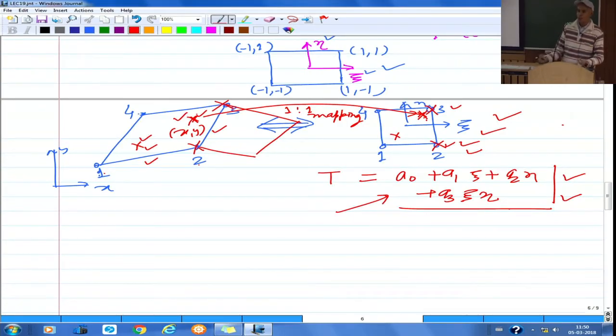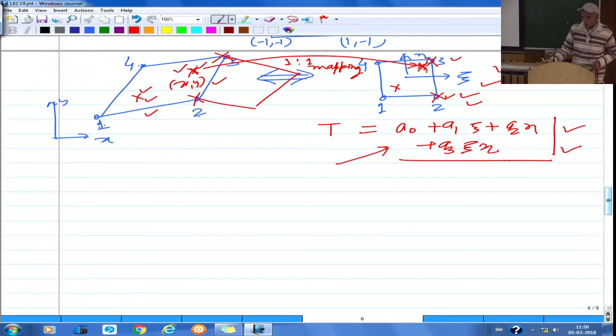And if you do the other way around, a lower order interpolation for x, y and higher order for the field variables or dependent variables, then it is known as subparametric formulation. Again, the most common one is isoparametric formulation. So when we discuss, we'll talk in more detail about the subparametric, isoparametric and superparametric formulations in natural coordinate space.